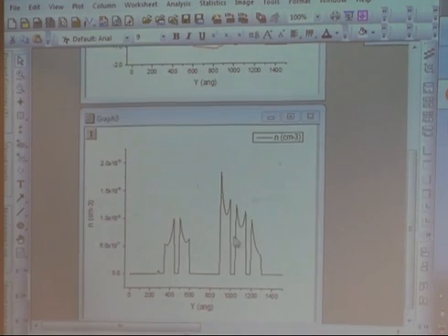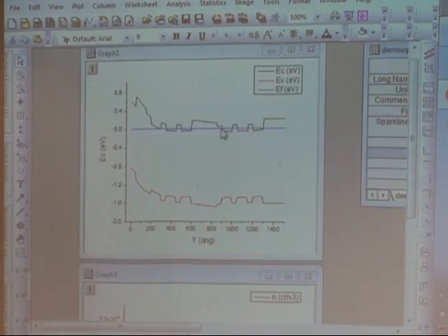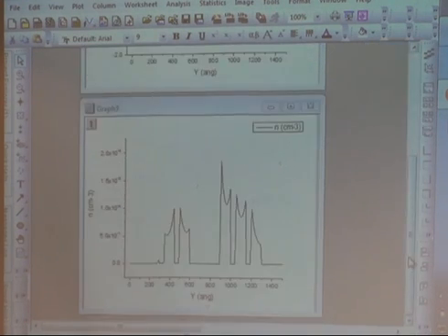And so this is a classical electron distribution in that region. Wherever there's a barrier, you see the conduction band here, and the Fermi level is hitting the conduction band. In classical physics, the carrier density goes to 0 immediately. But if I turn the quantum on, it will smooth out very nicely.